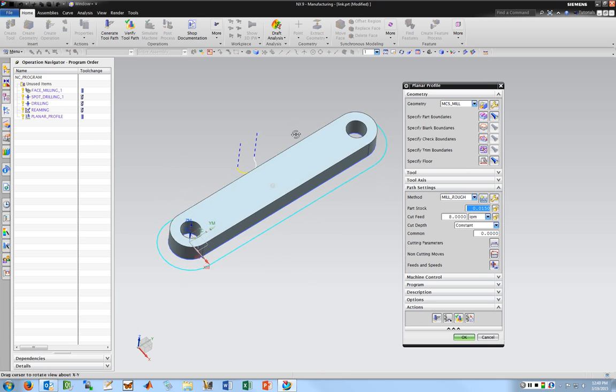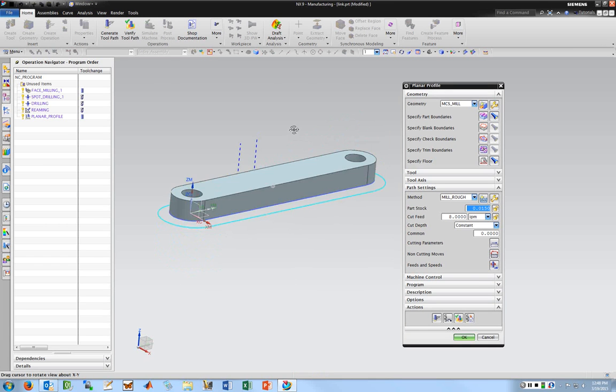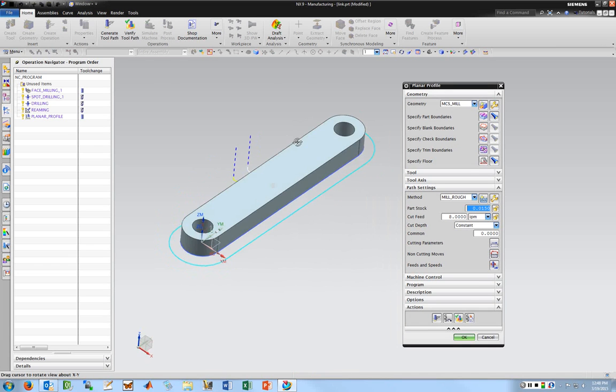So I'm generating that. If you did that with a 1/2 inch end mill, it depends on if your settings are set up right and you know what you're doing, you could do that no problem. Generally you're going to step this though, especially if you're in a machine where you can't use coolant, or you're doing something high strength. So generally I'm going to use different levels of cutting. So you can easily set that. So note here it's got cut depth constant.